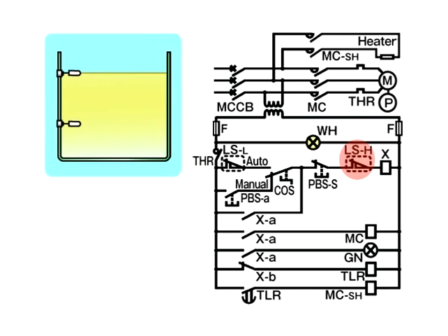As a result, XA turns off, and X does not remain in self-holding state. The MC coil is demagnetized as XA turns off. As a result, the MC contactor turns off to interrupt the supply of power to the motor, bringing pump operation to a halt. As XA turns off, the green operation lamp goes out.